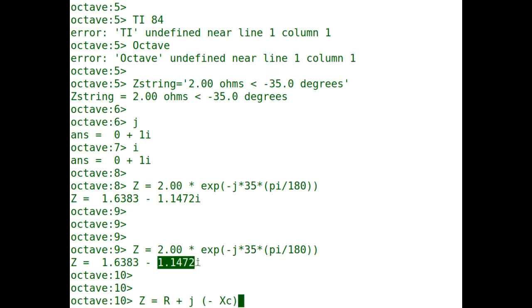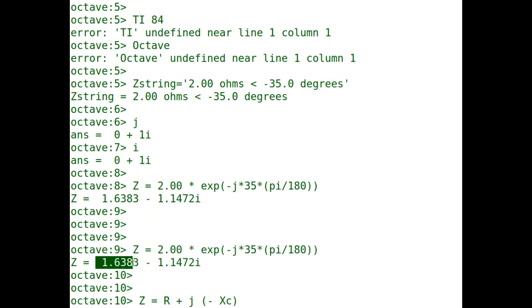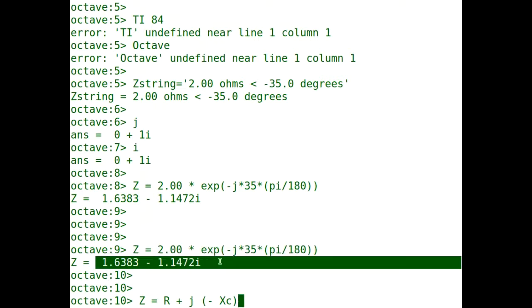The total effective amount of reactance in that circuit is capacitive. Because it's a negative number, I know it's capacitive. Or because the current is ahead of the voltage, Eli the Iceman, I know it's capacitance. And so therefore I have this minus X of C in my answer. So this is the impedance. This is the polar form of the impedance. This is the rectangular form of the impedance.